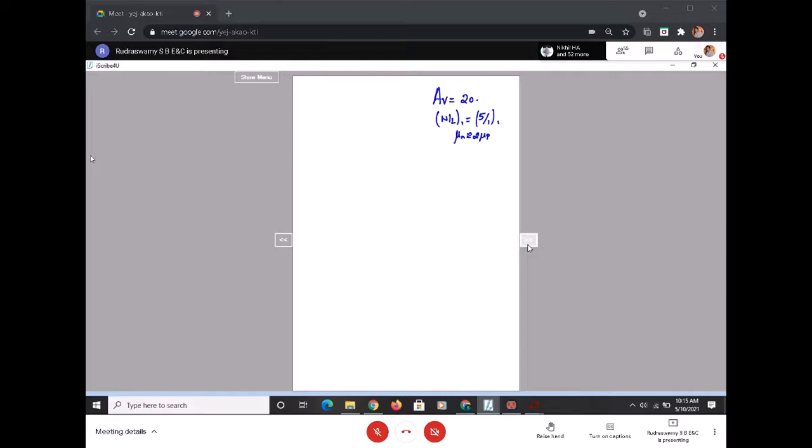You can change. When you're designing, don't use twice mu p. You can use 2.5 times mu p, and you can vary and see whether there is any change that is happening with respect to gain. If you want exactly the designed gain, you can just vary this mu n with respect to mu p and you can get it.